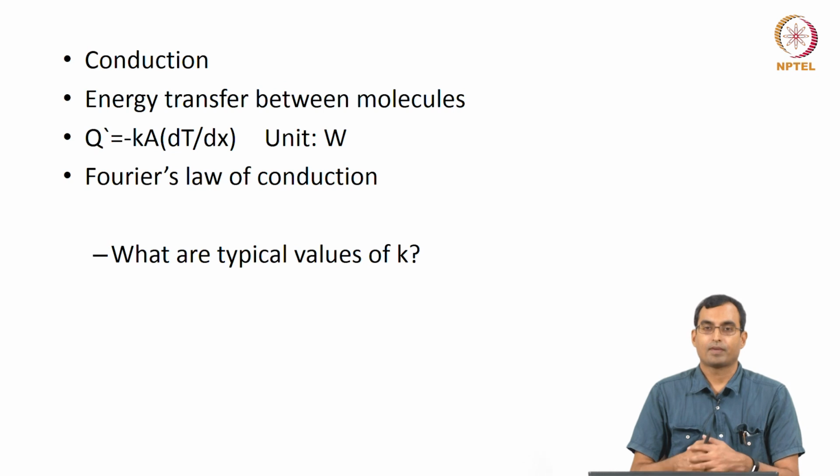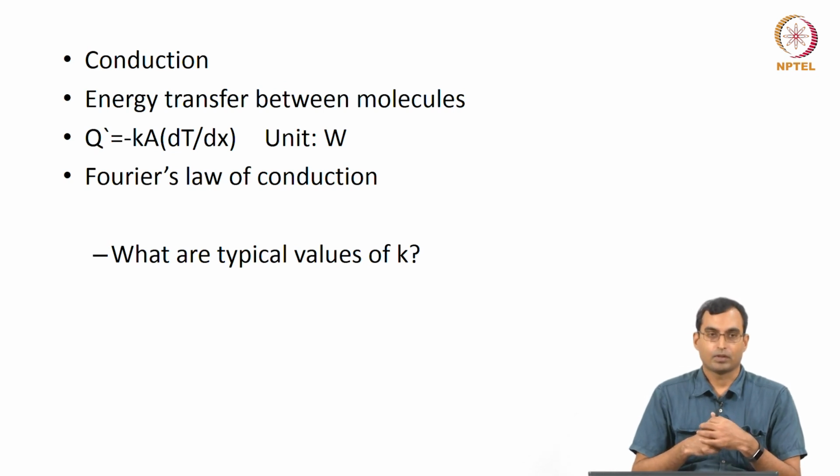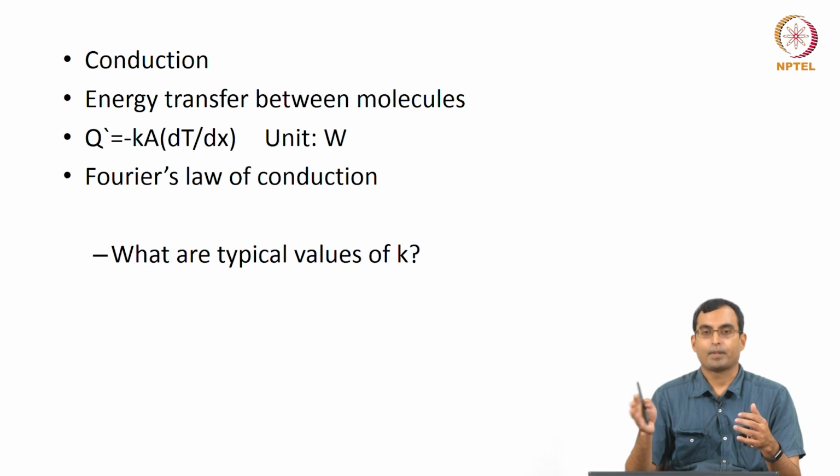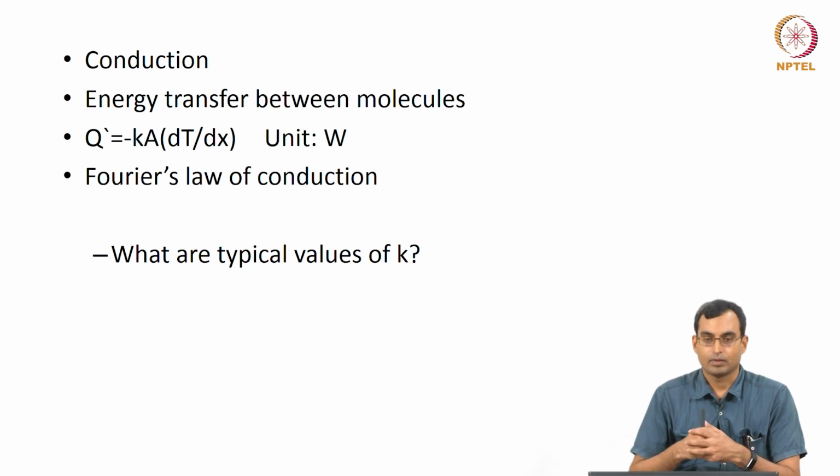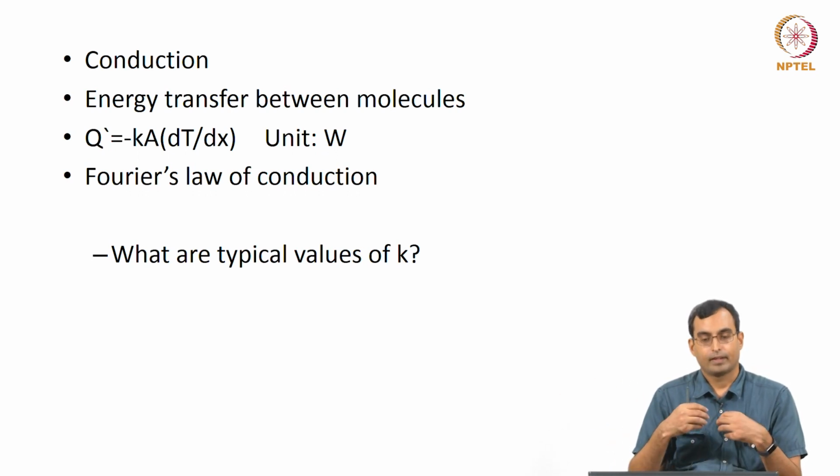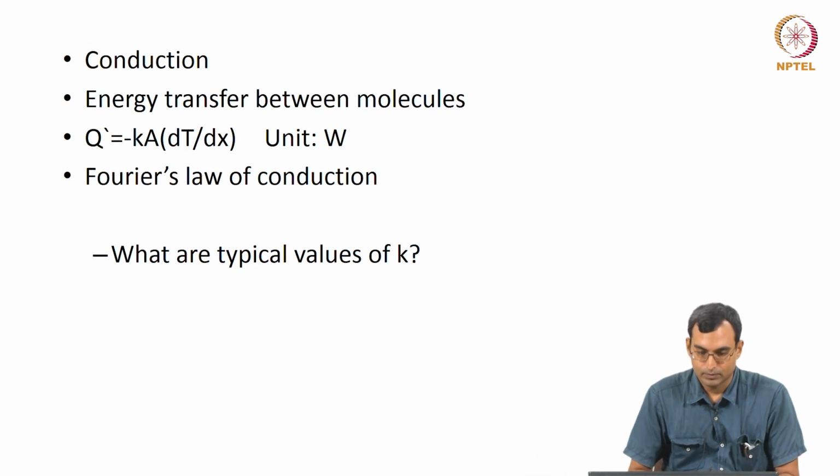When we talk of conduction, we are talking of energy transfer between molecules. The molecules, for example, in a solid, cannot move too far away, but they can vibrate and transfer energy to neighboring molecules. In a liquid or a gas, they are free to move more.